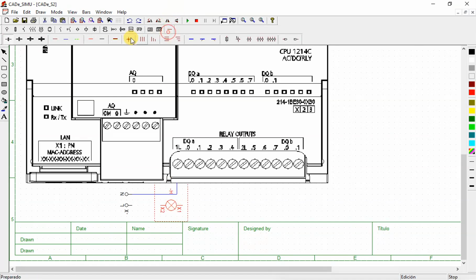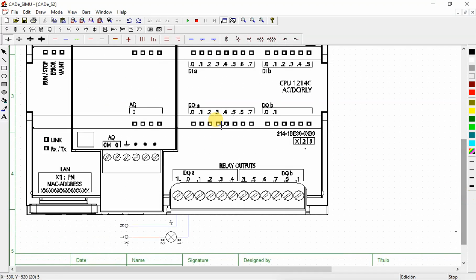Whereby now on this lamp I'm going to give live here, then I complete this side from the relay. Okay, this side is going to come as a neutral because we have fed in the neutral. So that means that once the relay closes, of course it's going to complete this common with this pin, and this will be completed and our lamp will light. So now that is how we do the connection.